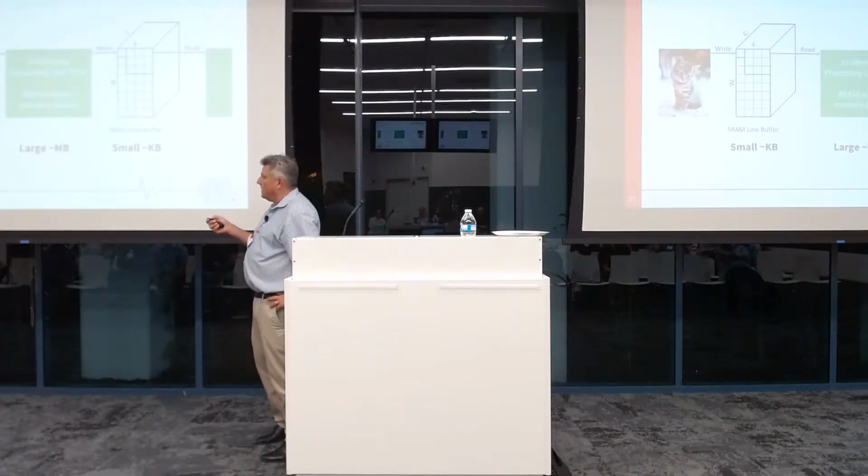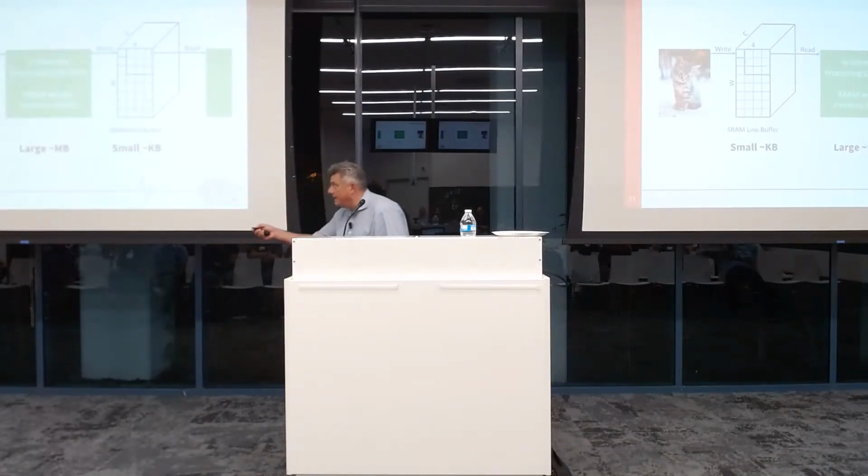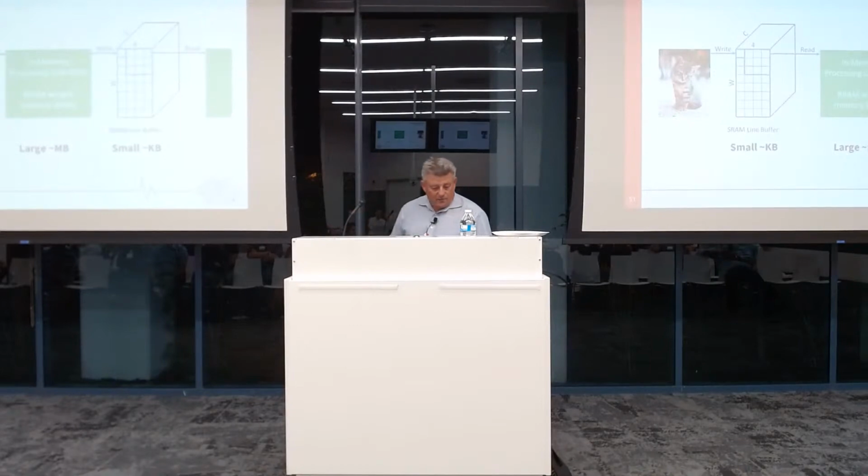And this cache has only to be large enough to keep a working set that keeps these input activations busy. So it's just a sub-volume of your filter. So it turns out these can be kilobytes, single-digit kilobytes, very small. So the access energy of this is almost nothing. And then all of the efficient multiply add happens here. And then you just repeat this and go through it.